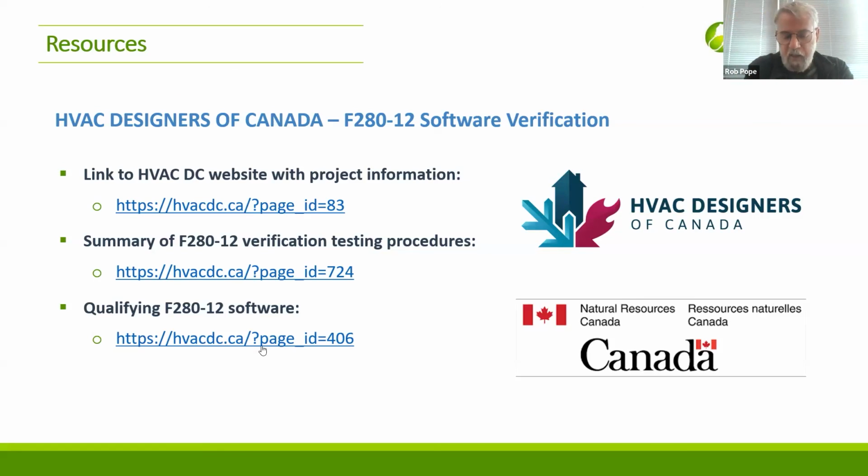So if it is not specifically in the BC Building Code, you need to reach out to the town or regional district or city, and usually it's published on their websites, and get specifically what the climatic data is for that particular location, and use that. That's your minimum required climatic data input. And then after that, it's just judgment.